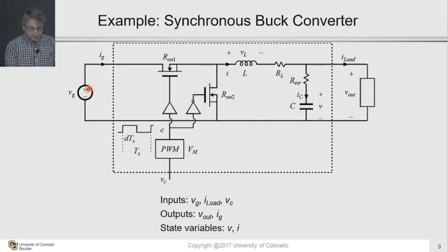You take the input voltage here, you switch these devices repeatedly at a switching frequency F sub S. You create a pulsating waveform at the switching node. The duty cycle of that pulsating waveform is the control variable that we refer to as D. And then you low-pass filter that pulsating waveform to generate an output DC voltage that is directly proportional to the control variable D and directly proportional to the DC value of the input voltage. So that's your buck converter in 30 seconds.